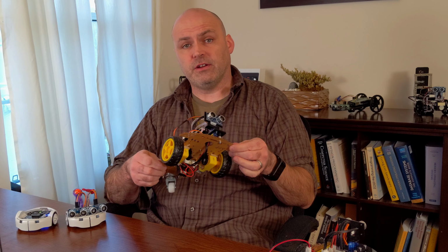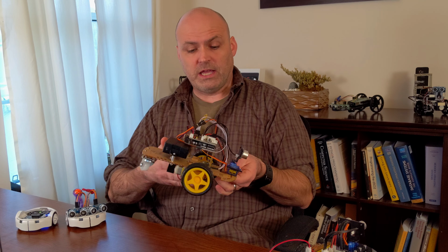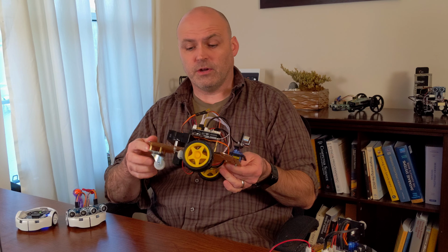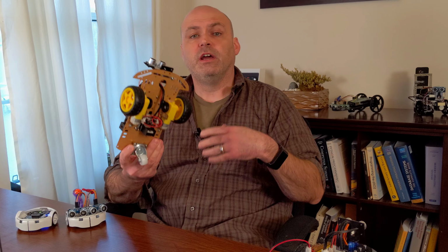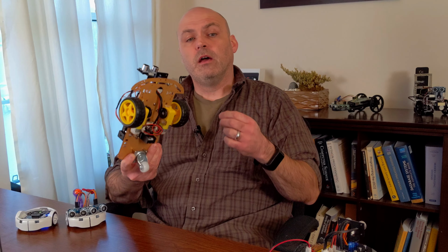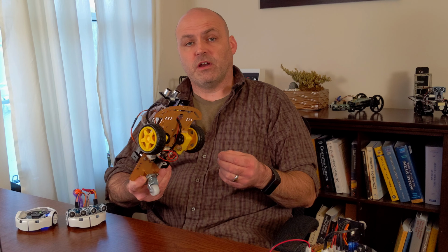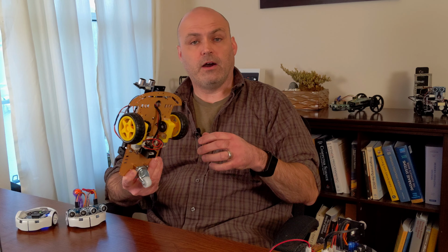You're going to have to tune it differently. Obviously the weight is different, the wheel diameter is different, the speed of the DC motors is different, how they respond is different. There's going to be lots of differences, but these are all things that you tune out. The algorithms that I'm going to discuss, starting today with how to convert the clicks of the wheel encoders into a distance like centimeters, that's all something that comes across.